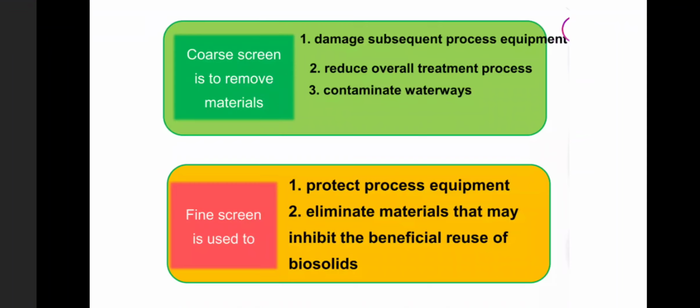When comparing the chain driven screens, the continuous belt screens provide higher efficiency because of this two-step protection, with an additional influent cover guard given. These ensure that the entry of floatable particles into the wastewater treatment system is prevented in a much more efficient manner.